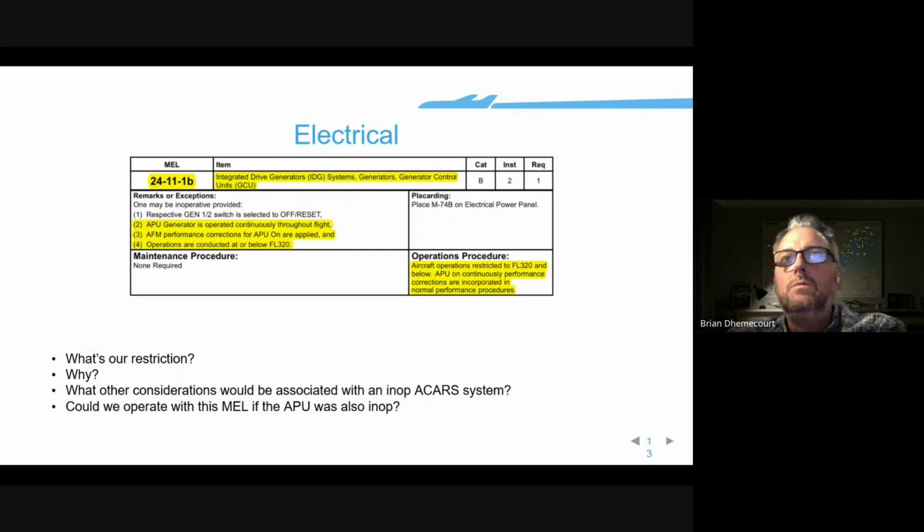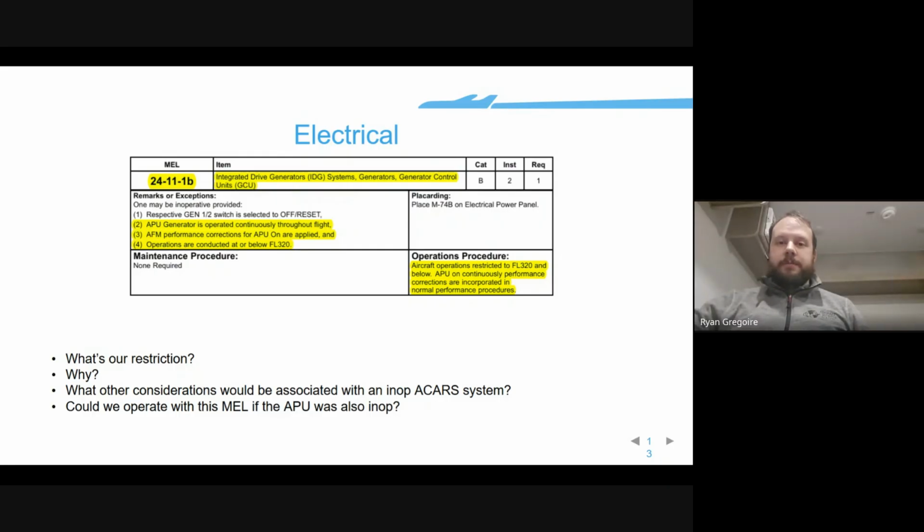You're close. So, you were right about fuel type. You were right about passenger handling. And then Christopher put in chat within fuel range. That's it. Yep. So those are our three factors that make an airport suitable for the purposes of diversion: correct fuel type, correct handling equipment for the passengers and the aircraft, and within fuel range.